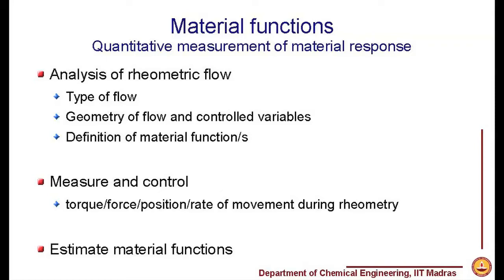In general, looking at the slide here, we will define what are called material functions, and these material functions enable quantitative measurement of material response, because we are doing analysis of rheometric flow correctly, because we have assumed the type of flow, because the geometry of flow has been designed appropriately, and the variables which have to be controlled are being controlled perfectly.